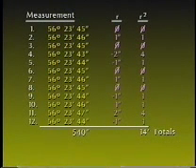Therefore, in our example of 12 measurements, it would be expected that 8 of the 12 measurements would fall within the range of 56 degrees, 23 minutes, 44 seconds, to 56 degrees, 23 minutes, 46 seconds, while 4 of the measurements would be outside the limits. In our example, 10 of the measurements actually fall within the plus or minus 1 second range.